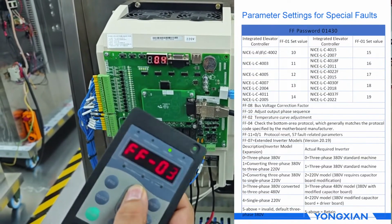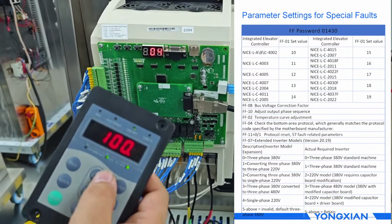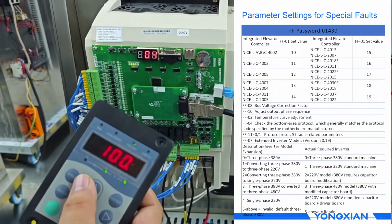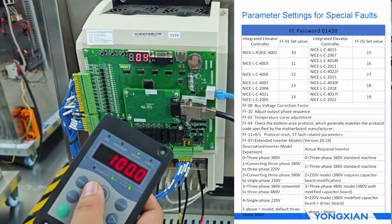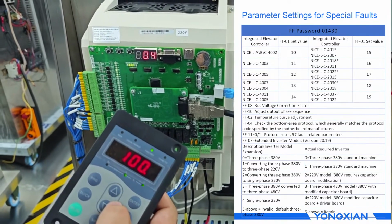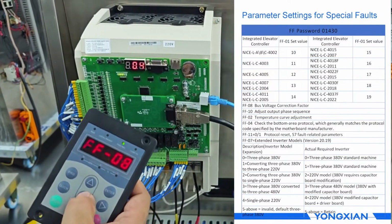Next is FF08. Usually, if our power supply has no problem but the inverter reports DC bus overvoltage, we can use this setting to check the bus voltage correction factor. The standard is to set it to 100%.